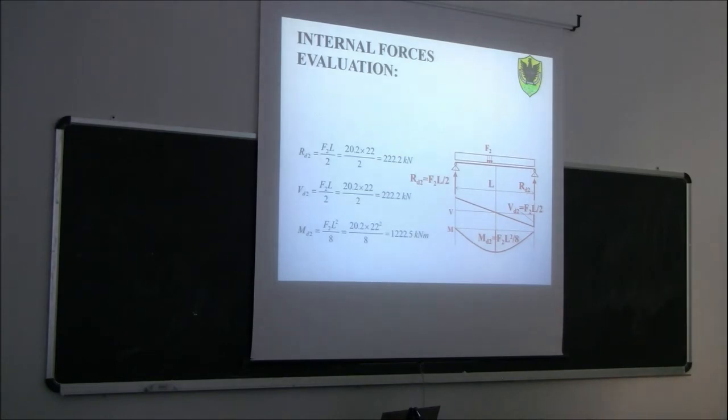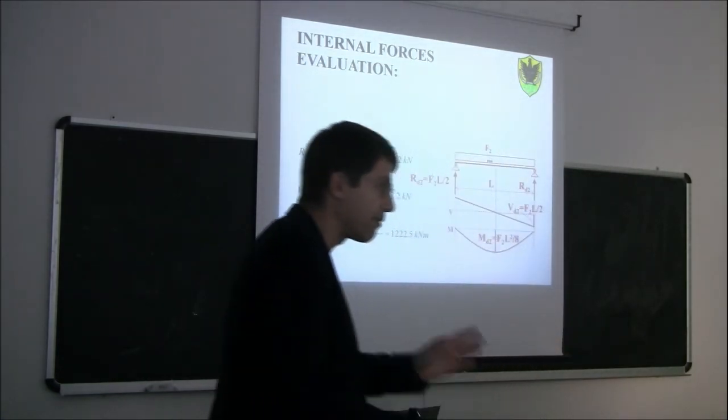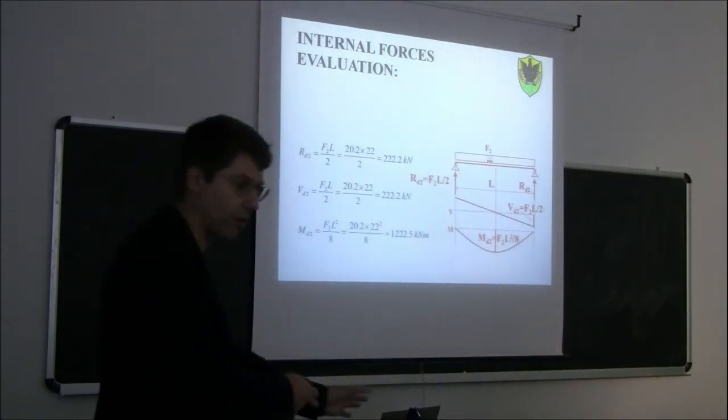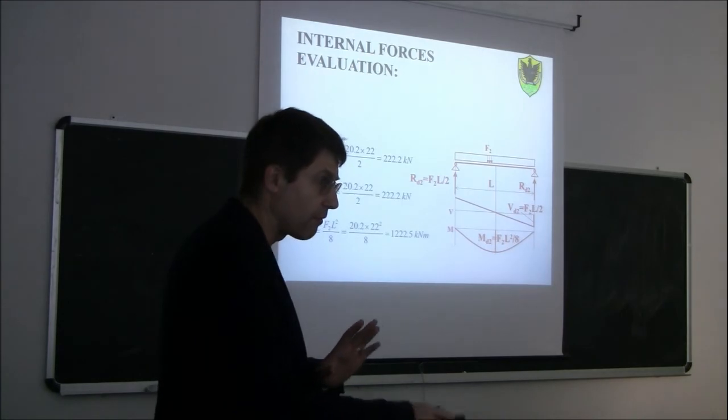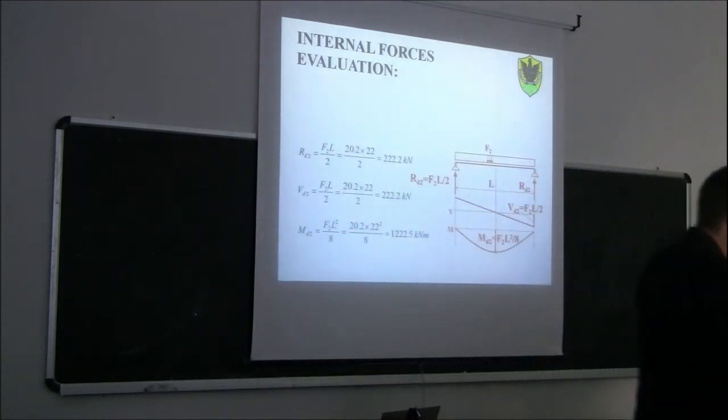Since instead we are using timber, how do we proceed? Remember what is the most important difference between reinforced concrete design and timber design at this stage here. Exactly. So for timber, unlike for reinforced concrete, unlike for steel, we have to check the maximum stress in the point.